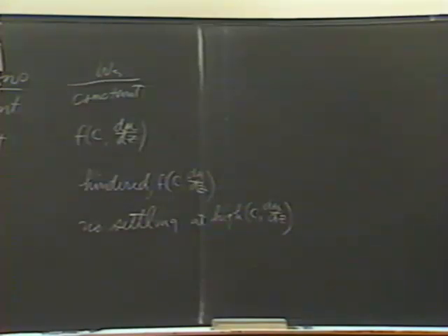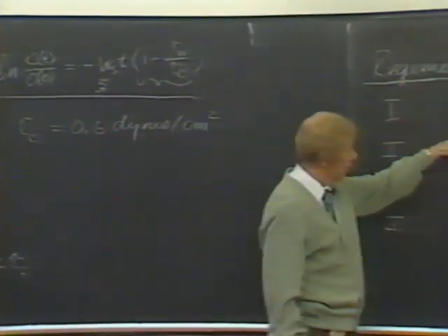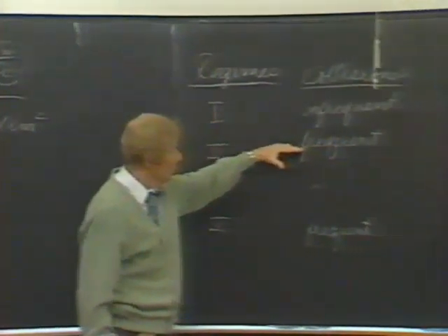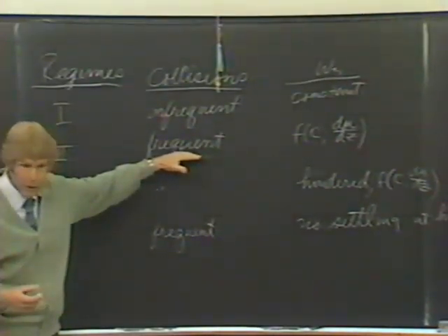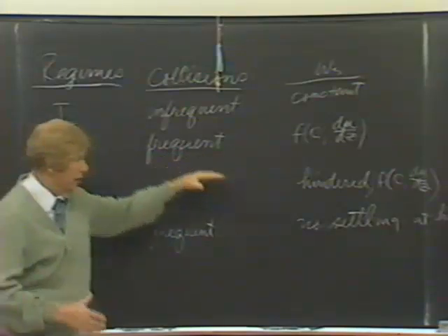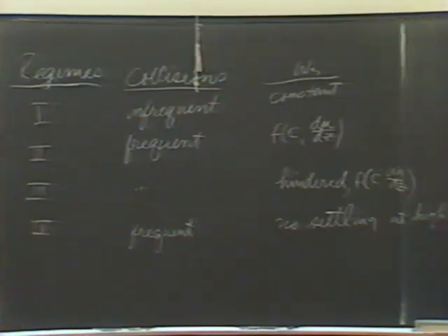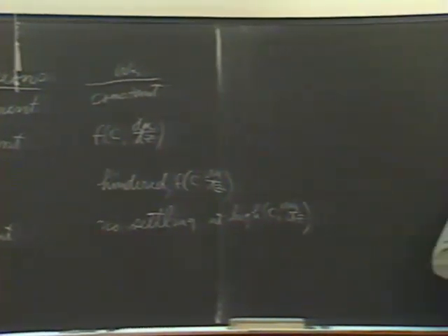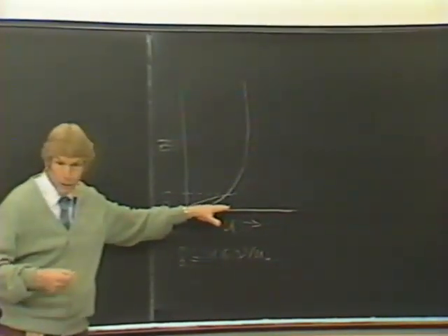Down here we have U is proportional to Z. But the velocity gradient here is the greatest, and the reason for that is that the shear stress within the fluid increases with depth. And the greatest shear stress is right at the bed. And this is the elevation we call delta. Z equals delta at this point.